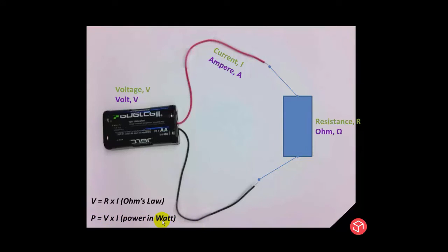So let's take an example. Suppose you apply a voltage of 100 volts to a load, and the current that flows happens to be 10 amps. So the product is 1000 watts, or if you like, 1 kilowatt. This power is related to how much you are charged for electricity. If such a load, that is a 1 kilowatt load, is used for 1 hour, it will consume 1 kilowatt hour. And in today's rate, it's about 10 cents per kilowatt hour.